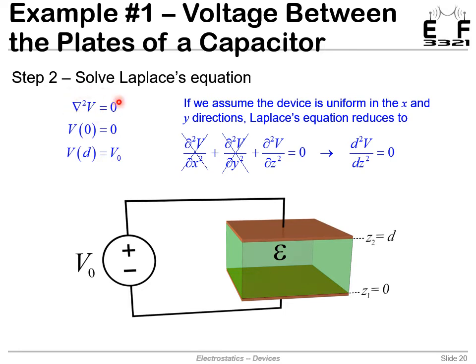The first thing I like to do is expand this into Cartesian coordinates, because we're using Cartesian coordinates. And since we're only caring really about between the plates and not really what's happening at the edges with the fringing fields, it reduces to a one-dimensional problem. And why am I choosing to ignore the fringing fields? Because that way overcomplicates the problem, and in my opinion, that's best done numerically, not analytically. So we're obtaining a solution in the middle of these plates, in between them. Based on that, we only care about this z or vertical direction, so we can just set the other derivatives to 0. Really what that's saying is we're analyzing a capacitor that's essentially of infinite extent in the x and y directions. When we do that, we only have one independent variable left, z. So our partial derivative is reduced to an ordinary derivative, and that's why we can use direct integration. We now have a one-dimensional problem here that we have to solve, and over here are our boundary values that will let us find the constants that we get when we solve this differential equation.